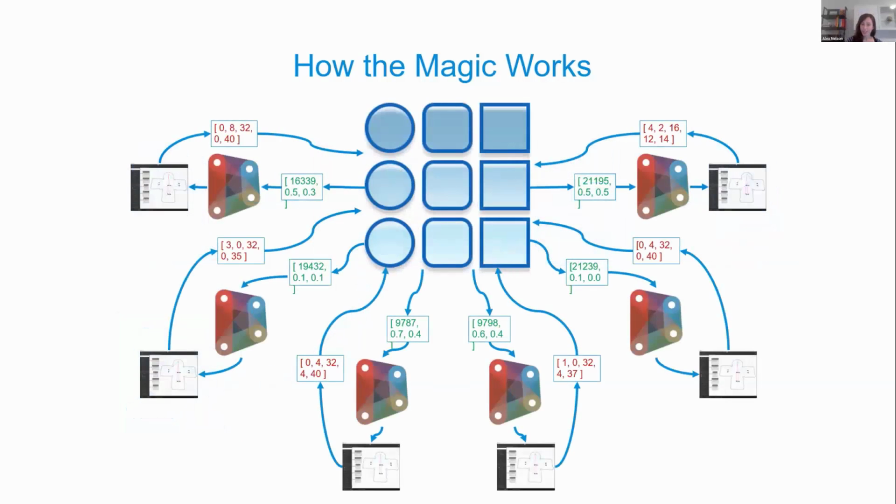How this magic works is that basically Generative Design effectively takes the Dynamo file that it was sent and a series of input values and sends them to a headless version of Dynamo Core, which we all know of as like a Dynamo sandbox, for example. And this will happen 6 times concurrently on every study type. So 6 Dynamo sessions will be open at one time with data flowing from Generative Design to each and then from each back to Generative Design. So the evolutionary solver knows how to explore the space.